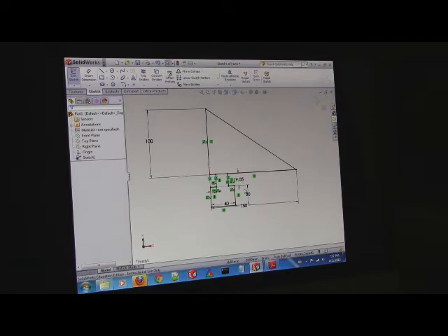Okay, select the little line, and then select the other little line. Are they actually? Can I see for a sec? So you're not zoomed in far enough. It's a little hard to see. Oh, I see. Okay. So click on that line, and then click on that line with Control, and then over here press collinear.